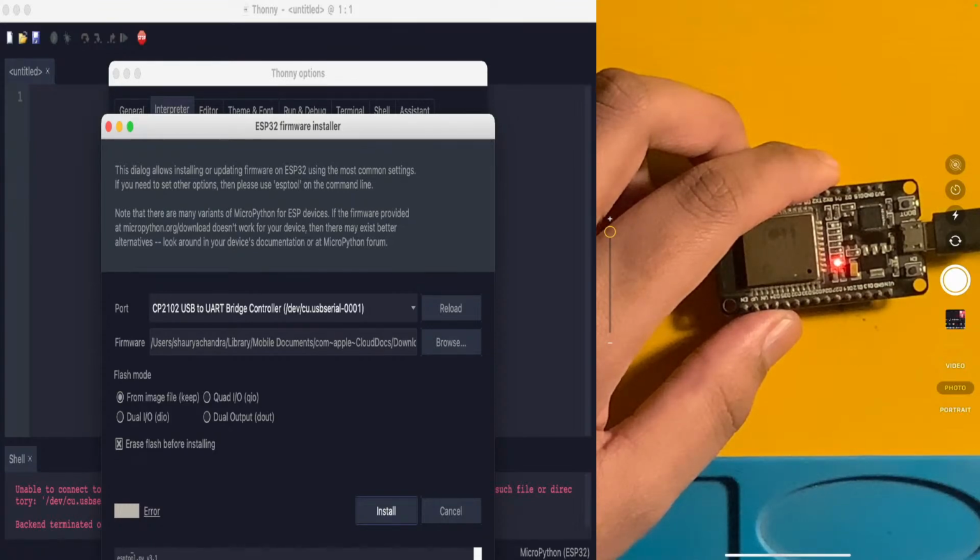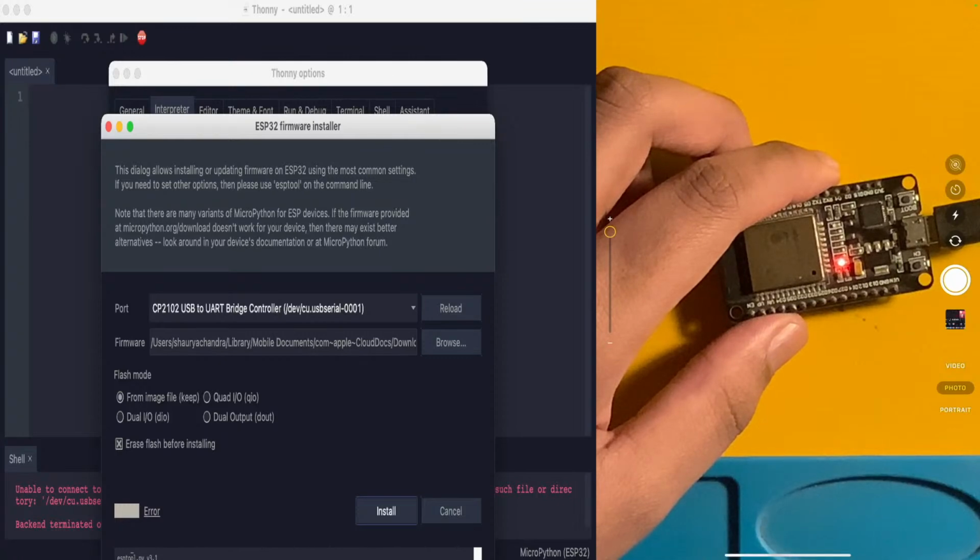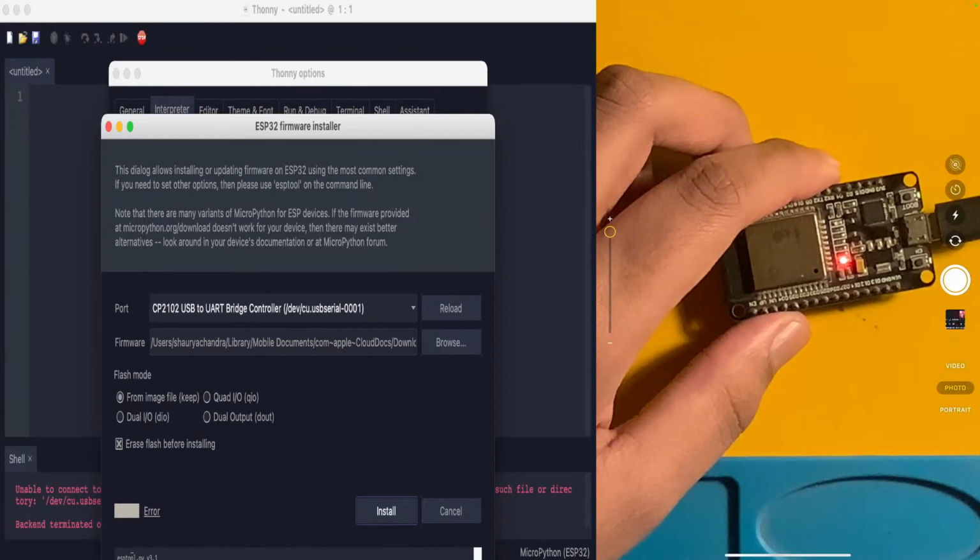The entire memory is the flash memory, but the CPU, your cores. I told you that our microcontroller ESP32 is a dual core microcontroller. That means it has 2 CPU cores. None of the CPUs knows what instructions to perform on startup. So the CPU asks the bootloader, which is again a memory partition. The bootloader is nothing but a memory partition where the initial setup is stored. So the CPU asks the bootloader, what do I have to do? The bootloader tells it to go to this particular memory address of the flash memory and start executing every code that is present over there.